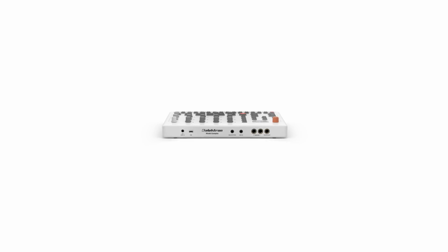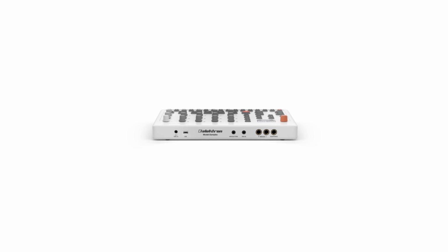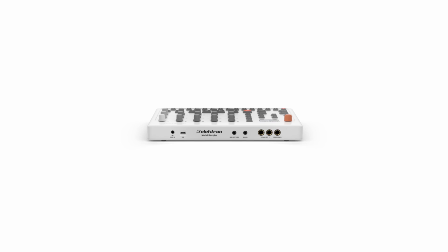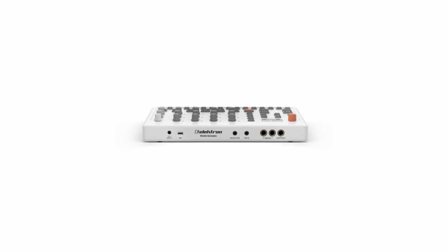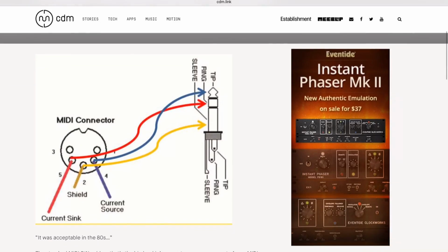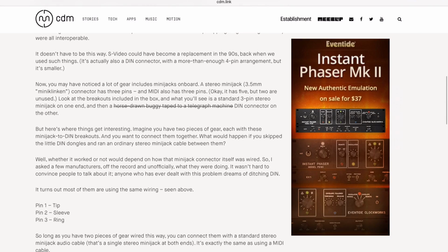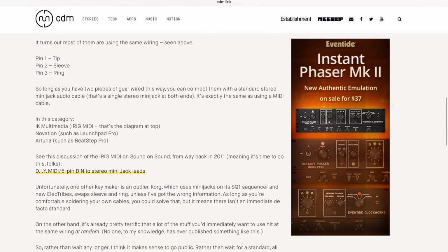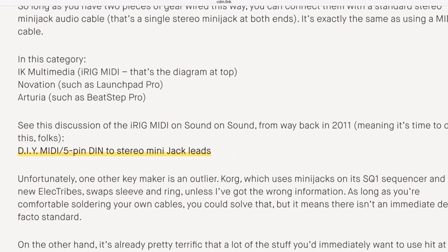The problem with MIDI jacks, and the reason there are so many dongle solutions, is that they add so much height to the PCB and the unit, and if you want to keep a low profile unit, it's very difficult to add a DIN jack. So this is a trade-off. But what's very nice about this implementation is that there are 2 standards for connecting the wires differently.